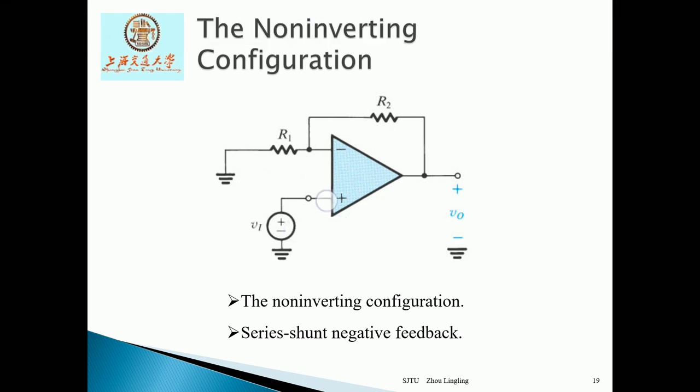It may be noted that it is also a negative feedback system, as the output is fed back to the inverting input terminal. As the differential voltage Vd at the input terminals of the operational amplifier is 0, the voltage at node A, V1, is the same as the input voltage applied to the non-inverting input terminal, and RF and R1 form a potential divider.